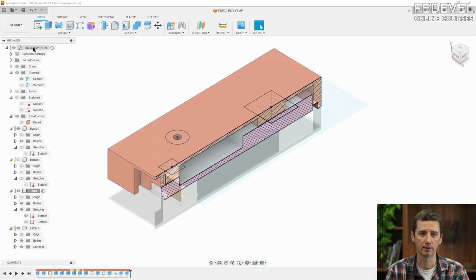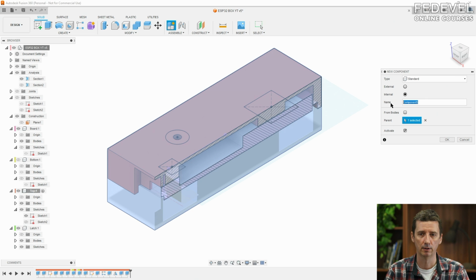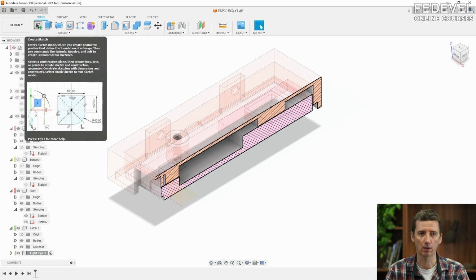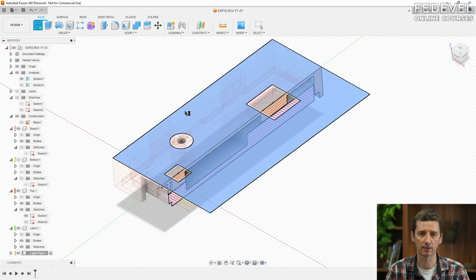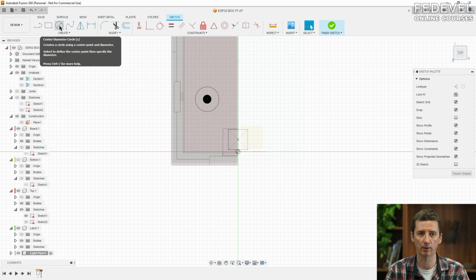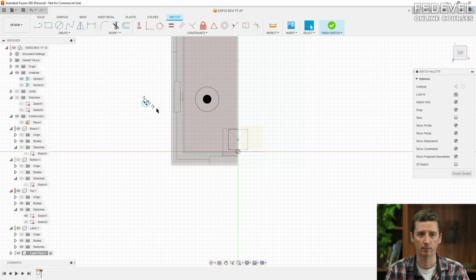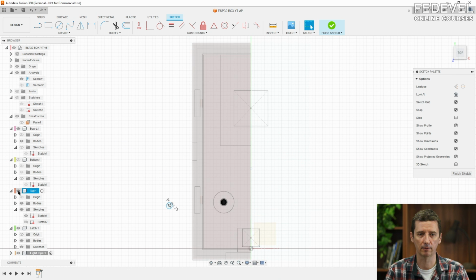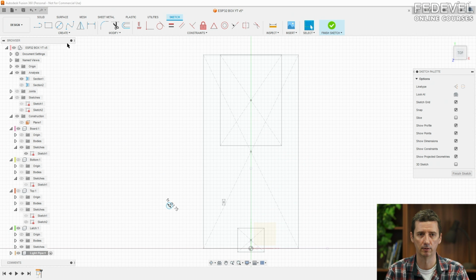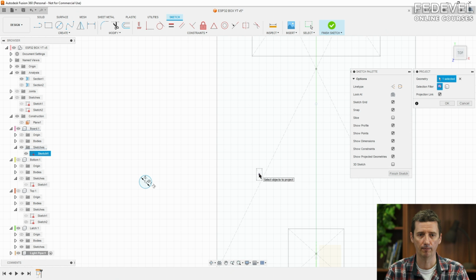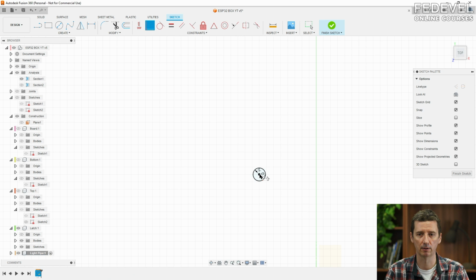Also add the filament, so new component. This is not really necessary, but when we will be creating the box, we would like to know the length of the filament which we need to cut. So I'm going to create this also as a component. It's a very simple component. Just I'm going to draw circle, place it again above the LED. So project middle of the LED, place this circle which will become filament, place it above the LED,